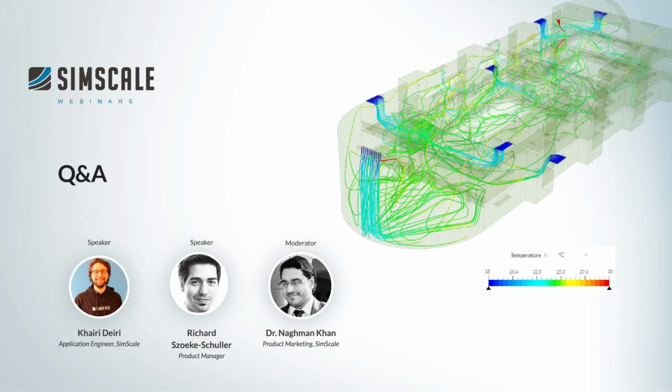Of course, with these simulations, what our clients usually like to investigate is which positions exactly are best to place those jet fans, for example. And we can replicate them using momentum sources. So basically we can add virtual bodies that represent those jet fans and supply a constant stream of velocity, so that we can really assess the overall ventilation inside that space, and where we get areas of low concentration, high concentration, and so on.